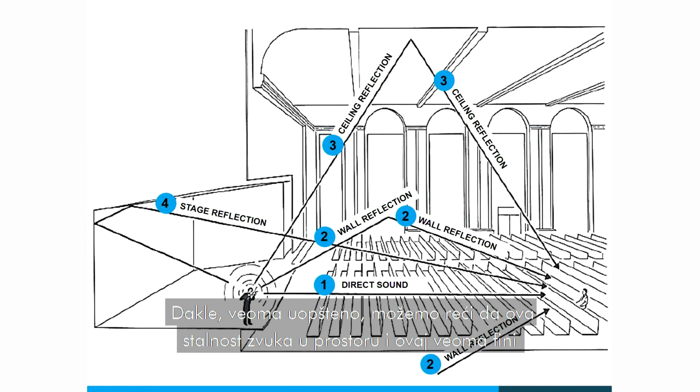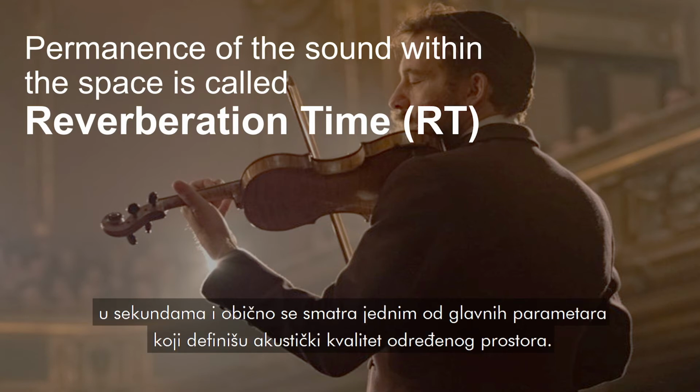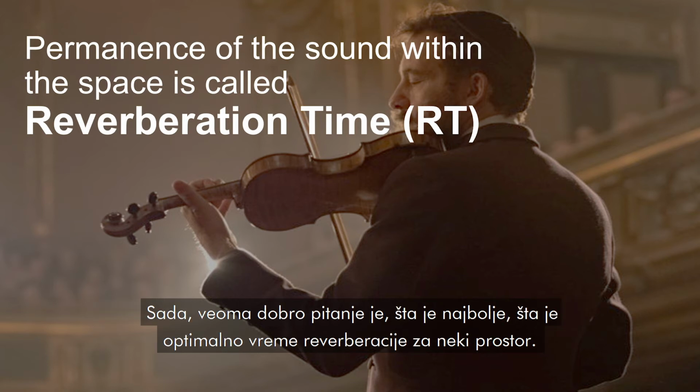So very generally, we can say that this permanence of sound within the space and this very fine balance between the direct sound and the reflected sound defines the quality of a sound within a space. And this permanence of sound within the space is what we call the reverberation time. And this reverberation time is measured in seconds. And it's usually considered to be one of the main parameters which defines the acoustic quality of a certain space. Now, a very good question is, what is the best? What's the optimum reverberation time for a certain space?